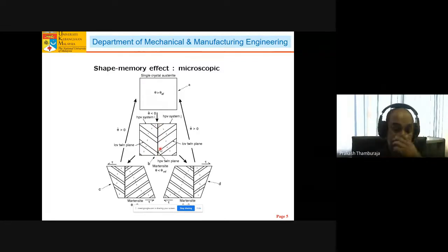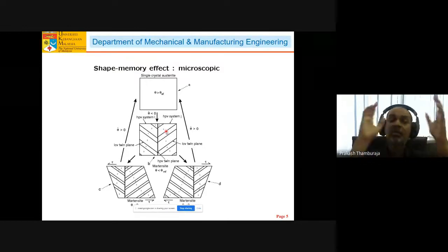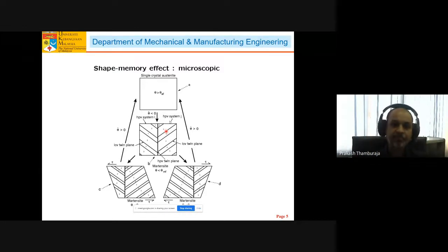If you look at the microstructure, within the plates they are also split by different energetically equivalent configurations, which are called variants. For example, this plate or system 1 here has variants 1 and 2, and this plate J has variants 3 and 4. They are energetically equivalent, but oriented differently in three-dimensional space. As you apply stress, the boundaries within the plates and between plates move as well.